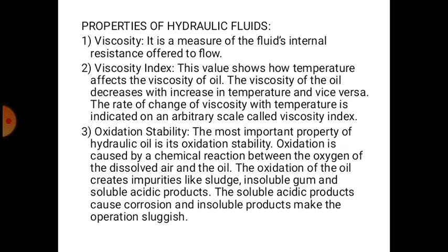So in a hydraulic system, we want to maintain moderate viscosity. It must not be too high or too low. If it is too low, there will be wear of the parts. If it is too high, there will be power loss.